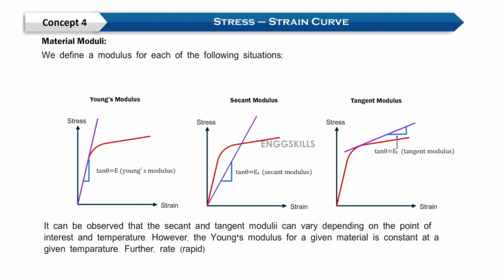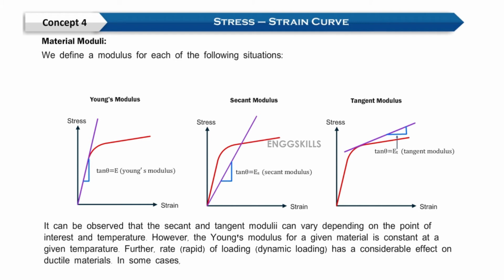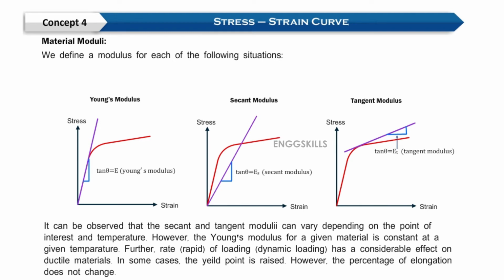Further, rate of loading has a considerable effect on ductile materials. In some cases, the yield point is raised. However, the percentage of elongation does not change.